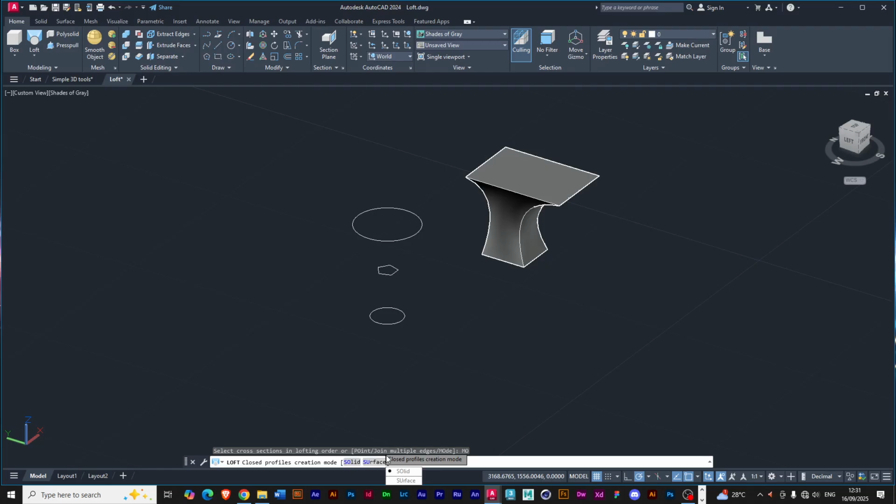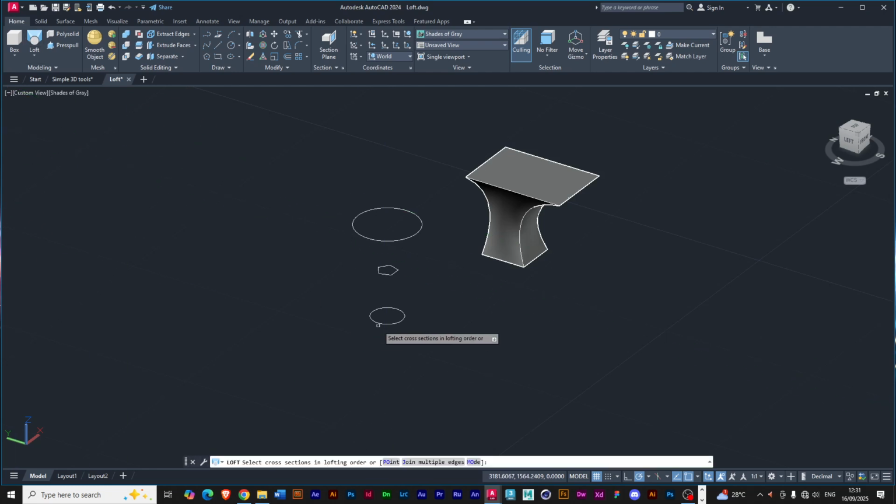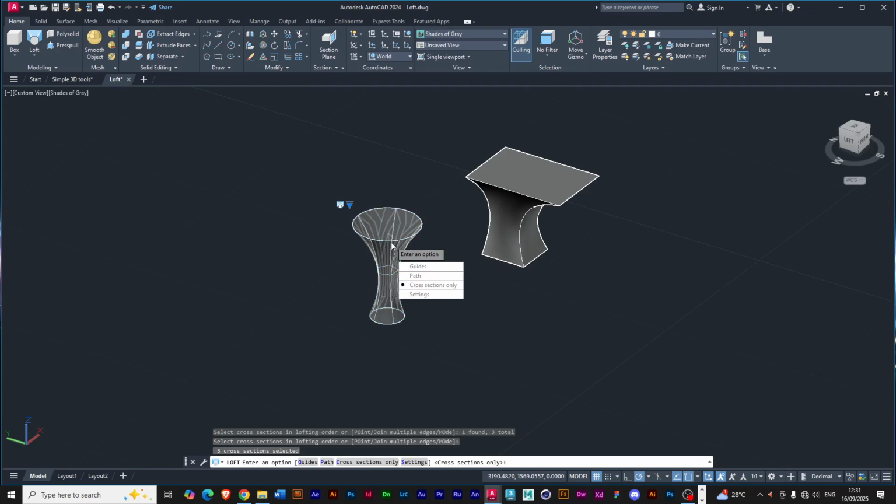Still those same kinds of options. But once you create your loft and you press enter, we now have all these other options too: guides, path, cross sections, or you go to settings and change some things. Click on this, it will open those options in case you didn't have them before. You click on the blue arrow, it will show you another set of options.